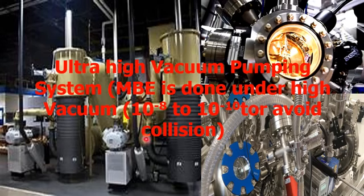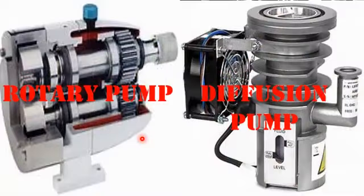Dear student, please note that there are some available pumps which are commonly used in different physical and chemical vapor deposition techniques, such as a rotary pump and diffusion pump. But the diffusion pump especially cannot be used in molecular beam epitaxy, because a diffusion pump is based on oil vapor phases, and they can cause impurity inside the reaction chamber of the molecular beam epitaxy.